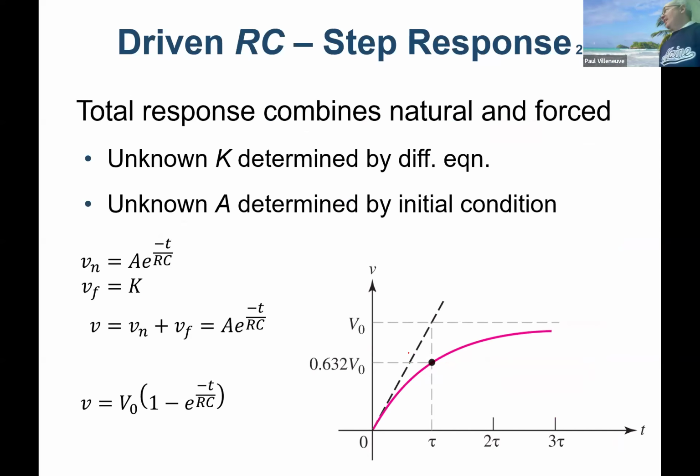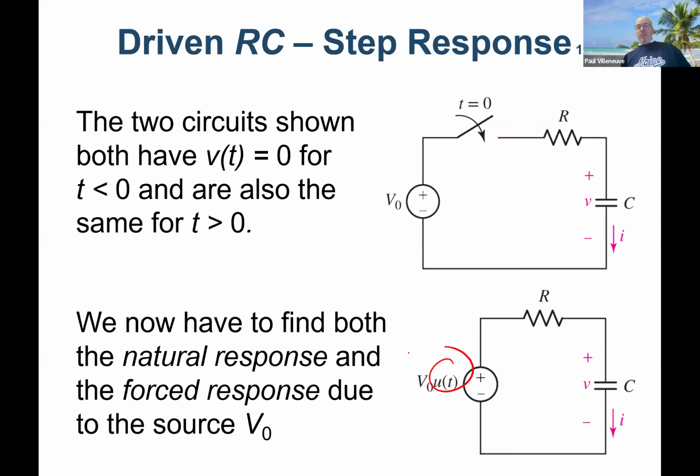So if we wanted to replicate our voltage, we know, or hopefully we know, that the voltage across the capacitor, VC, if it's initially uncharged, is going to be 0. And then eventually, what does that capacitor do when it becomes steady state? What happens to a capacitor when it's fully charged? It becomes an open circuit, right? No more charge going in there because you can't stuff it in there.